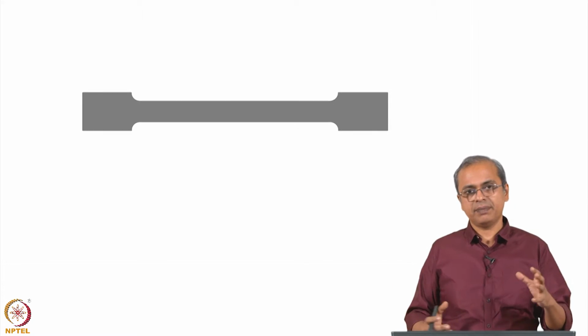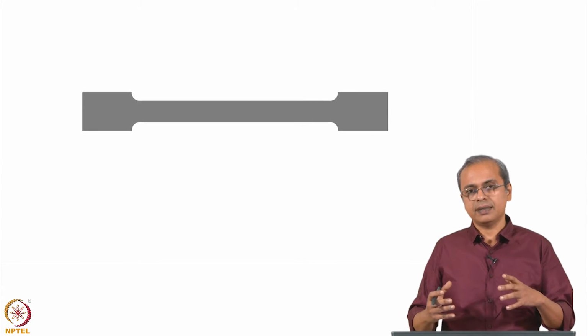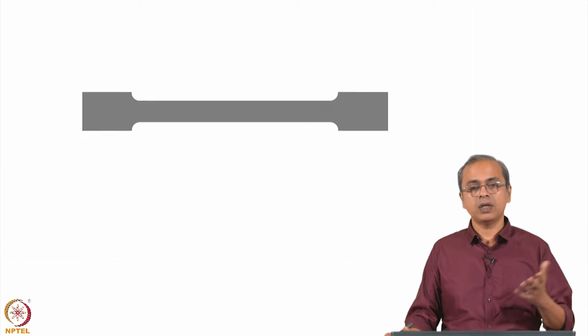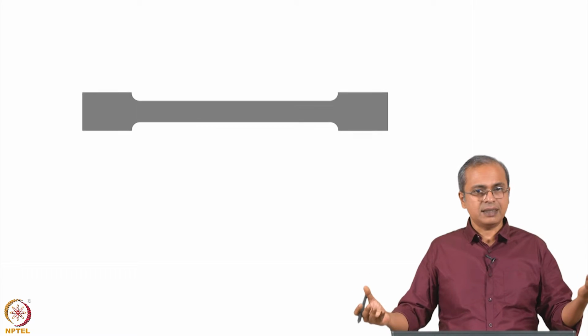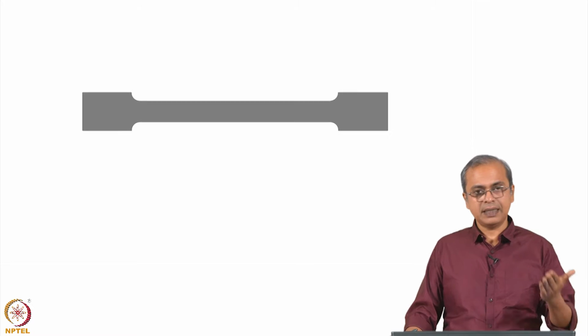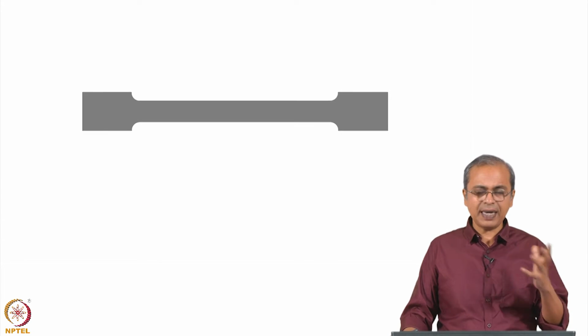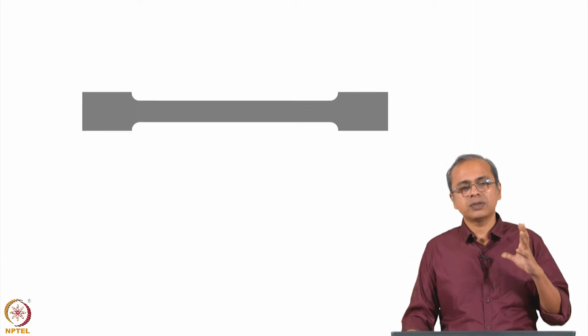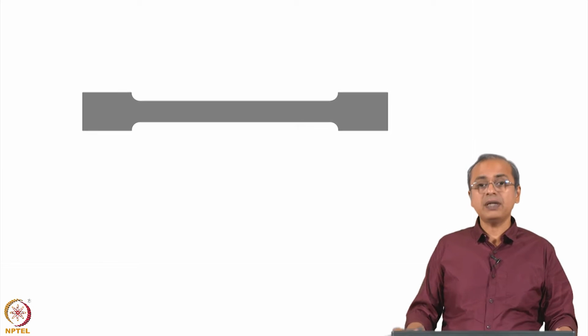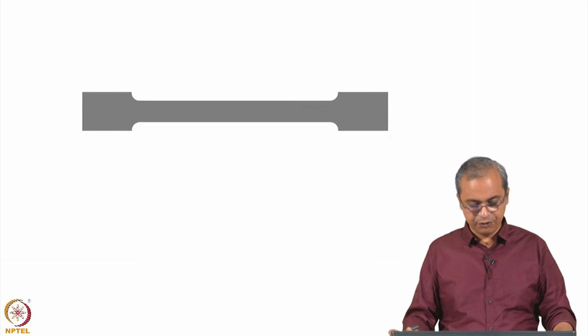Elongation is a much more generic term, and like I said, you could have 100%, you could have 1000% and so on, so it is a very wide range. So, would you call 100% plastic and 1000% superplastic? Where is that line of demarcation? Just looking at elongation does not convey a clear enough picture as to when you should call something superplastic deformation.